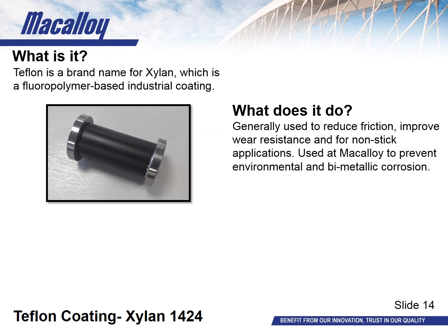It is worth noting that the Teflon coating is an alternative to your standard isolation sleeves. This is useful for two reasons. One, so that you don't have to worry about losing the isolation sleeve on site, but two, because you're able to use the same gusset plate dimensions as you would as standard, so you don't have to worry about modifying the plate and hole size.